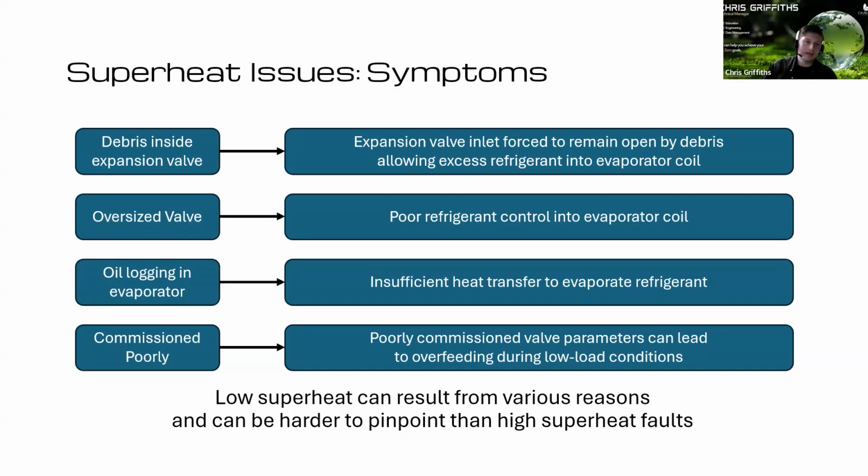So honestly, having that visibility over a prolonged period of time is invaluable. And for troubleshooting, literally yesterday alone, I was chatting to one of my former apprentices who's now an installation engineer, and he was commissioning a small freezer room, and he was wondering how long it was going to take before he could head off because he's got a 2-hour drive home. So I dialed into the site, had a look, and you can see it's dropping by 5 degrees Celsius every 5 minutes, basically. I was like, well, you're plus 2 degrees now. You've got to get down to minus 21.